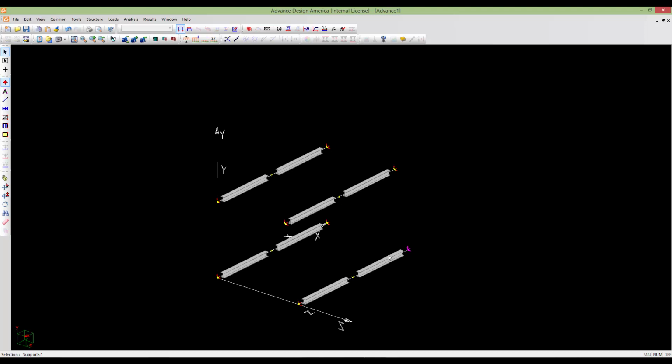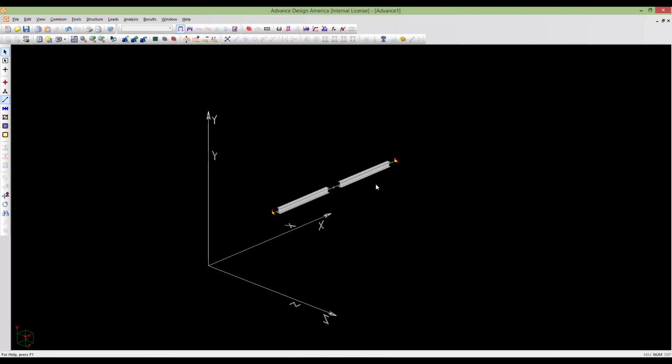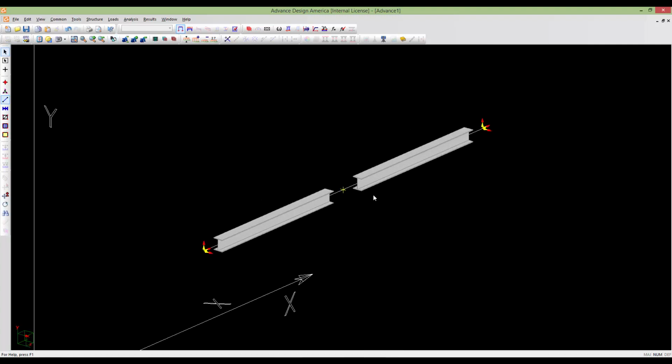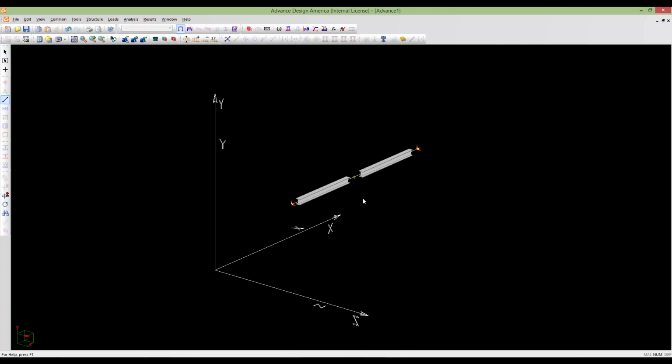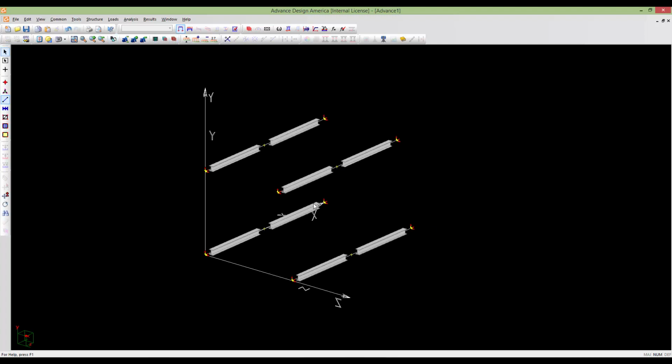For example, I'm going to give you an example. Let's say I want to mask these two members here. You can always select the member with Control, and if you press the M button or use the mask option here, as you see, these members will be masked like this and the other ones will be hidden. So you can just work on this part of your model. To bring all back, you can unmask them or push D to bring all back.